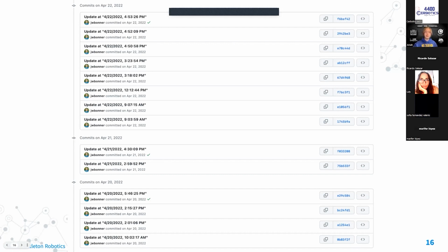So we have a separate system for competitions where it's particularly critical to be able to replay every match, even if we're making rapid changes to the code. So we created a VS Code extension, which automatically generates a commit whenever we deploy. So here's an example commit log from the championship. All of these commits go on a branch in our repository, which we later squash and merge back to main, so we're not cluttering things. But the result of this is that every version of code that has run on our robot during a competition is available to us forever in order to do log replay.